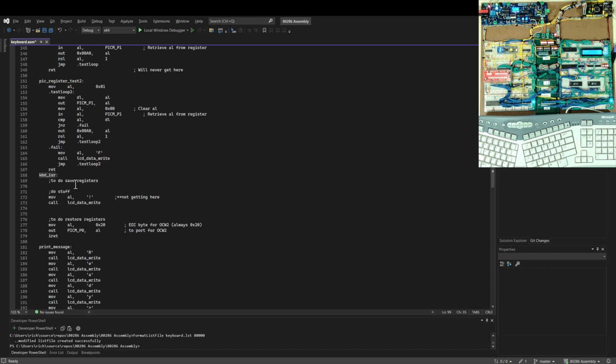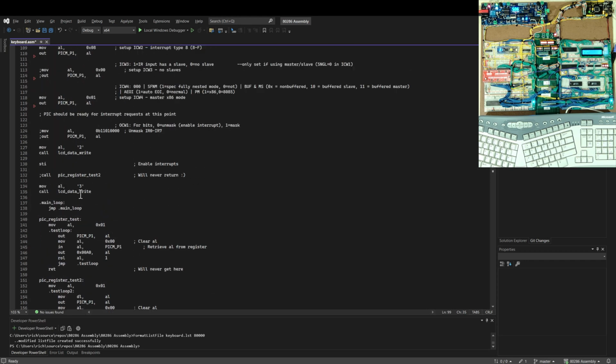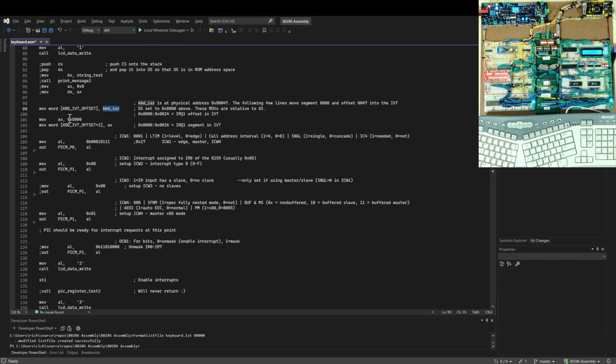And I am going to take that location, which is 2 bytes, so a word, and I'm going to write that word of data to that offset, which is at the beginning of my RAM. I then move to the next location in RAM and write out an 8000. That is my segment. And so as I've come to learn with the Intel programming, very different from my 6502 world that I came from, I have to give it an offset here and then a segment here.